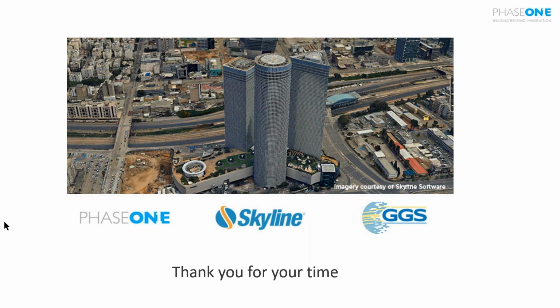There's a question, if you scan a large area at different times of day, how do you adjust for shadow direction of the objects in the images? So this gets addressed both ways. One is in the aerial triangulation. Usually if the shadows shift, there are other objects and features that are utilized as tie points, especially when you view them from 5 different perspectives, and those get filtered out.